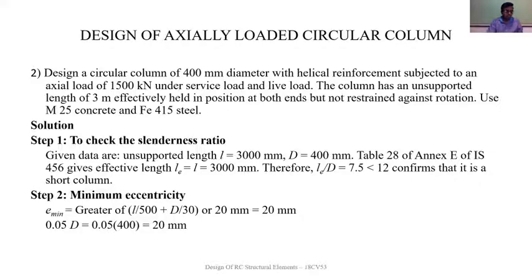with helical ties are: the columns with helical ties generally take more load than tied columns. That is, the circular columns with helical ties have more load carrying capacity than rectangular columns tied by rectangular ties, due to the additional strength of the spiral contributing to the strength of the columns.